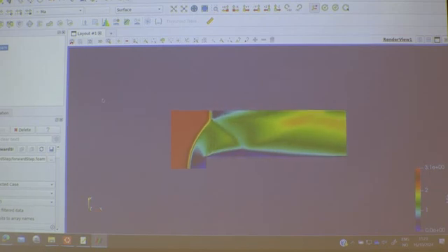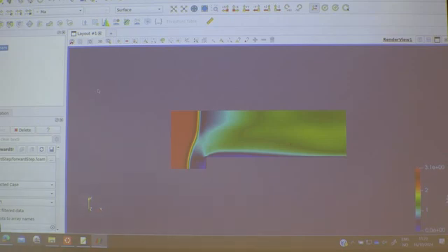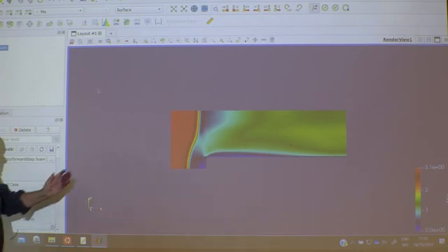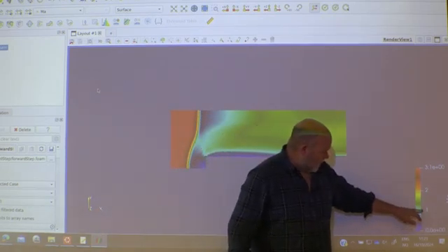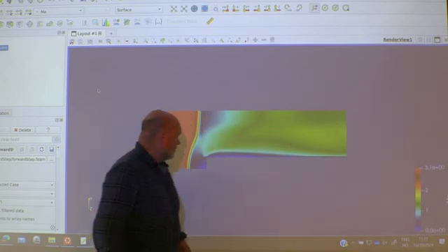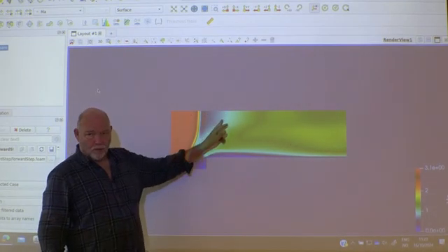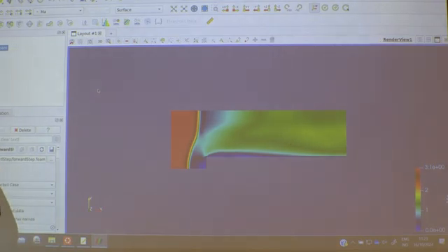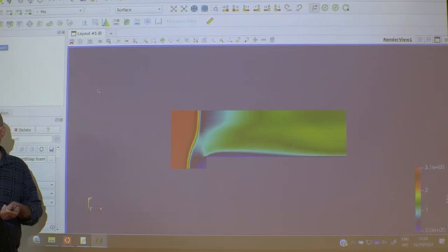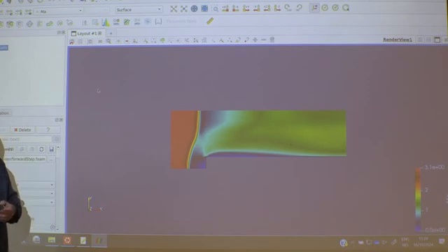And this is something we have to look at as a steady state, or at least towards a steady state setup. You see the Mach number goes down. And let's see, we have one roughly this color. So here we'll have a Mach number of 1. And that's something physical actually, when you have a nozzle and you have the smallest area, you will always find Mach number 1 there, regardless of whatever driving force you have in the system. We're going to see more of that one later.